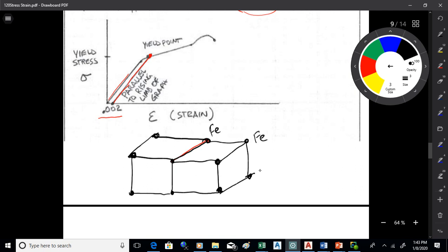Now what happens when you make steel is you put carbon in there. The iron is what makes up most of steel, and it creates a pattern like that. Now in the middle are where the carbon atoms go. And what they do is they stiffen up the iron. Pure iron itself is kind of soft and malleable. It's not as strong as you would think. When you start putting carbon atoms in the middle, though, you stiffen it up.